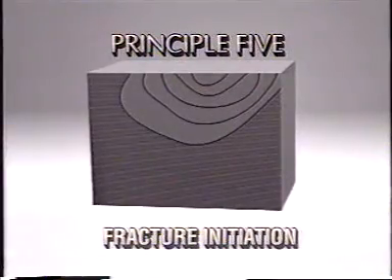Five. Fracture initiation usually occurs at or near the surface. This is because in most engineering situations, the surface is subjected to the greatest stress. For example, in bending or when stress concentrations are present.